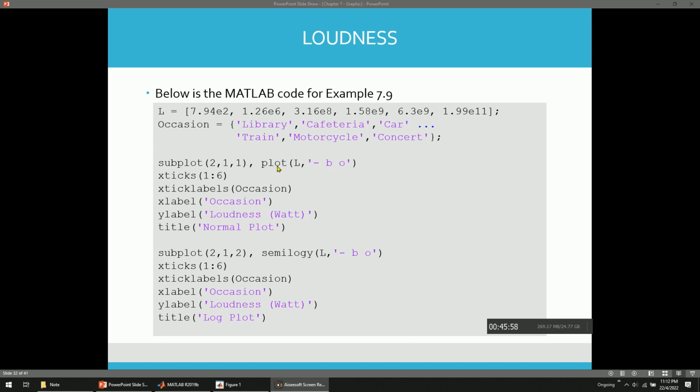So you have plot y. This is the data first. You collect the data, this is the data, you write it in MATLAB. And then the occasion, this one is the string data. And of course, this triple dot is basically, if you don't want to make it a long code, you can just put the dots here. I think this one is missing a comma.